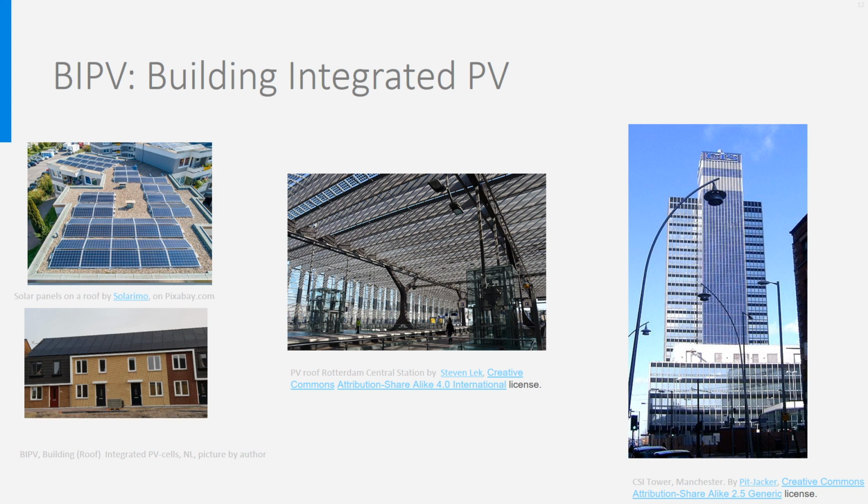On these panels, only half of the surface is covered by PV cells, letting the light pass and producing shadow during the warm weather. The other half produces electricity. These semi-transparent PV cells can be used as cover for atria or vertically as solar blinds. The right picture shows an example of vertical panels used as coverage material for the CSI Tower in the UK.